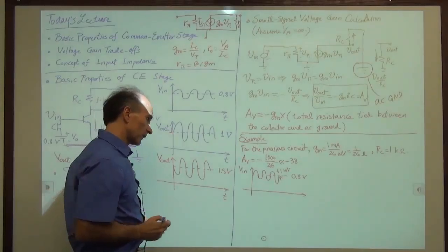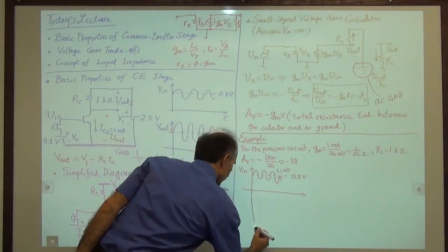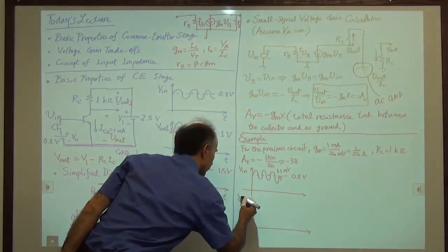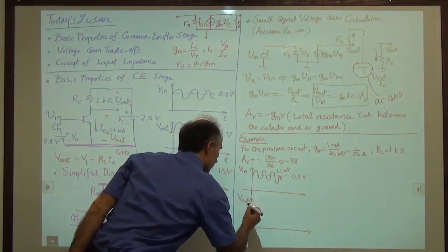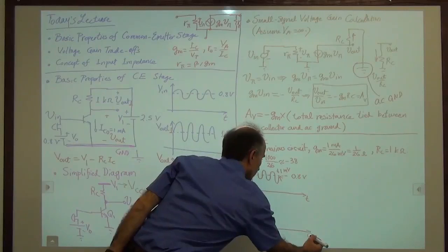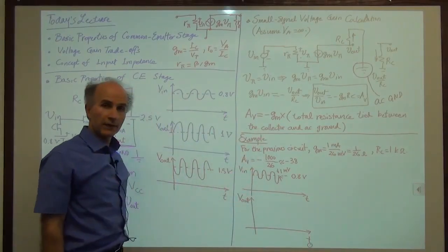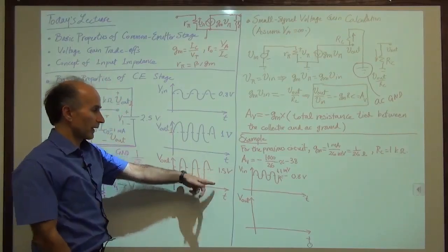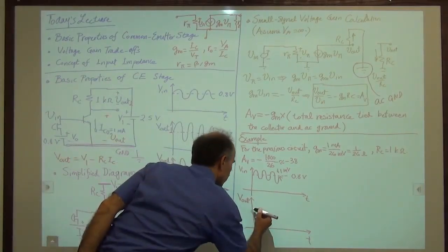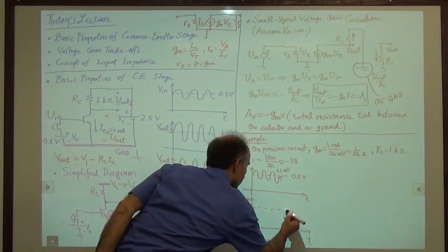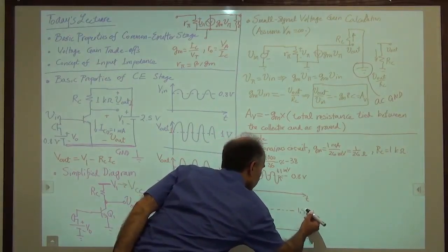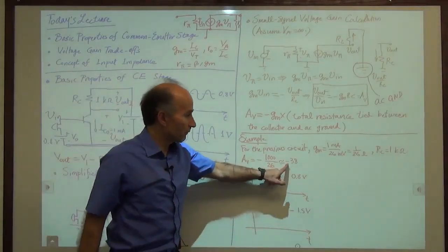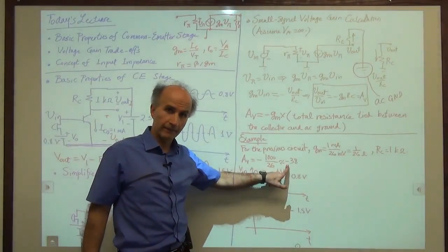All right, so this goes to the amplifier. And out comes V out. Now again, this is the entire V out. And the way we think about it is without a signal, we just have the bias values. So remember that V out without the signal is 1.5 volts. So just keep that there. We have 1.5 volts. And then we have a gain of minus 38.